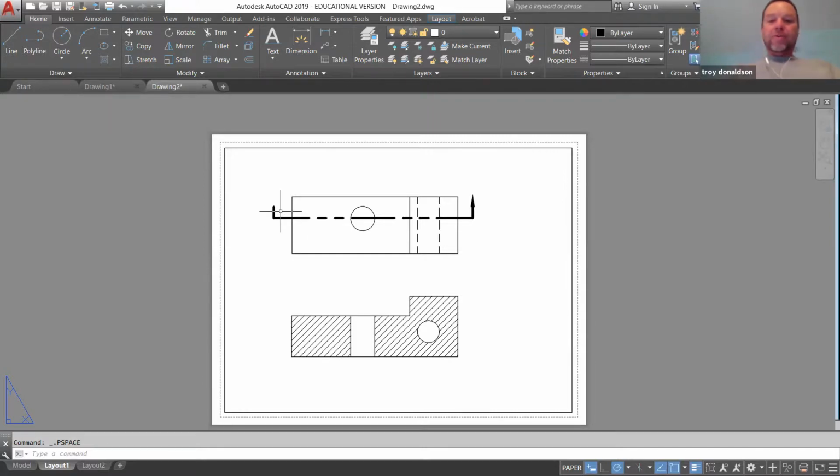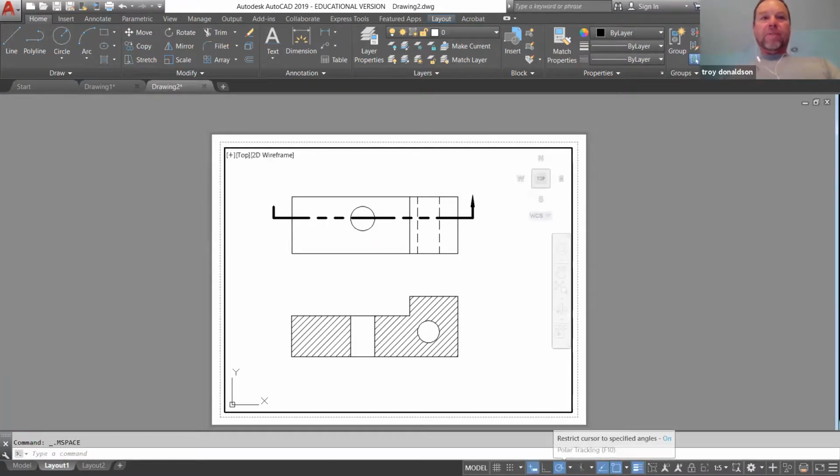So what I did then, I worked the other side and I said, oh, sorry, here's my space, polyline, and started here. Now I know I want that W starting width to be like 1, ending width to be 0, and then I can drag it out a little bit. So I like that much better. Then I would erase this arrow. And then I would copy this arrow. Now, you might be thinking, gosh, what a pain. There's got to be a simpler way. There really isn't a simpler way. This is the easiest way.